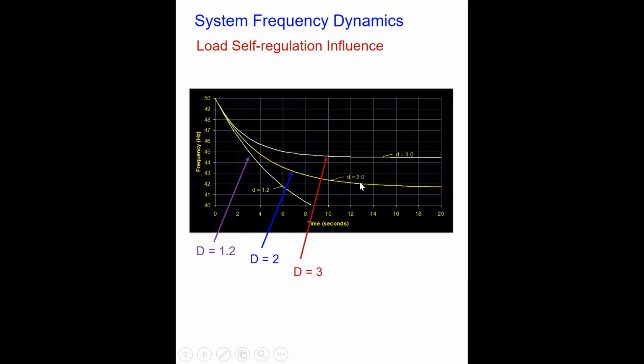If you have a low value of the load damping constant, then the decay in the frequency will be sharper, so you have more decay in the frequency.